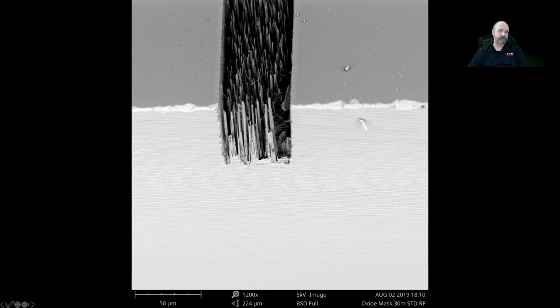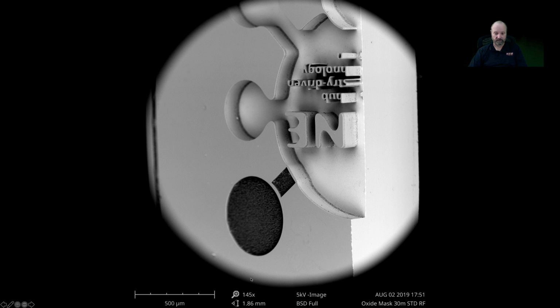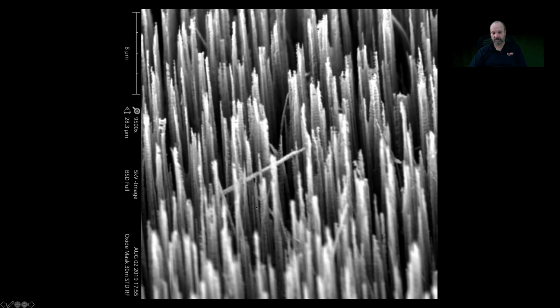What happened here is we didn't clear all the oxide. So we had little tiny specks of oxide that we didn't etch away where we wanted it etched away. Those little specks remained on the wafer surface and protected the silicon underneath. Here we cleared, so we could etch all the way through. Here we left some oxide behind, and we get this weird grass effect. That was really a combination of the photolithography with the subsequent silicon dioxide etching. And there's a close-up of it and a further close-up.